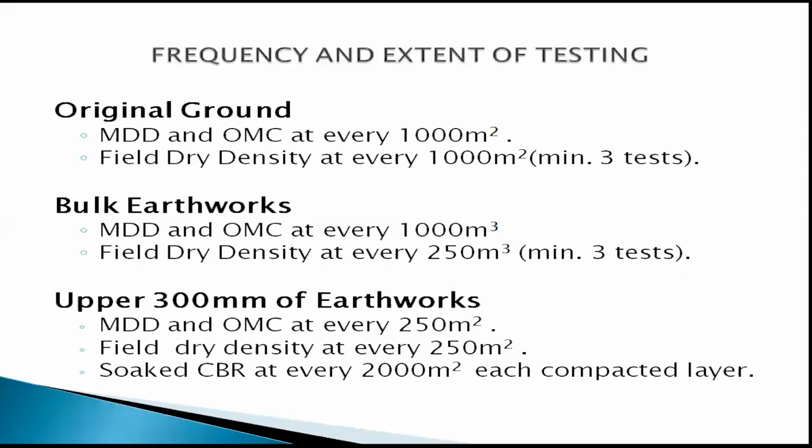And for under the upper 300 millimeter of earthworks, we need to also do the soaked CBR at every 1,000 meters squared of each compacted layer. Here, and under the upper 300 millimeter of earthworks,